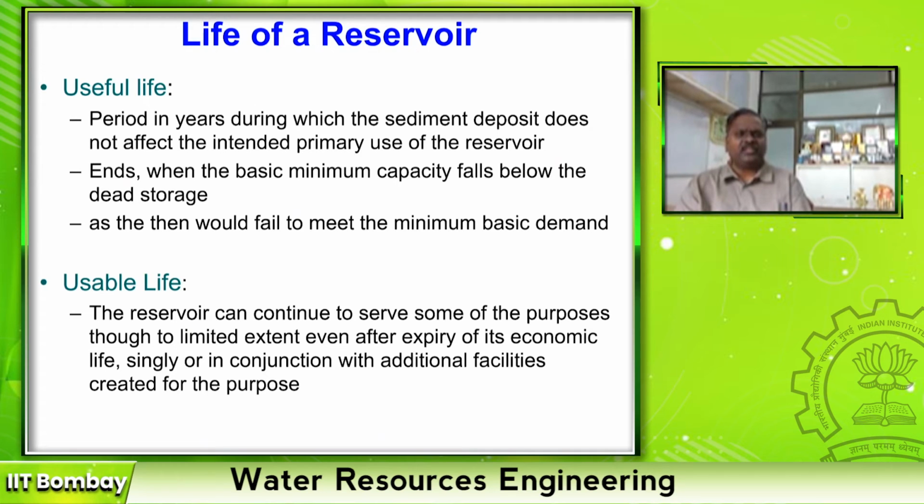Until that period is called useful life. Then usable life is how long the reservoir can continue to serve. Even if it has come down only up to the dead storage, I can still draw the water and use it after treatment. Such a period is included in the usable life.